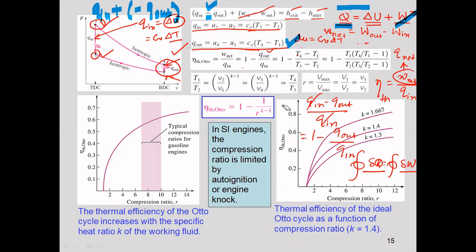Okay. So if you have an engine, in that engine, even if you do not conduct an experiment, you can measure the volume. Right or not? Even if you do not conduct any experiment, simply you can measure volume without conducting any combustion, etc. So if I can convert the temperature ratio in terms of volume ratio, then we can easily guess what is the efficiency. Because you see, if we keep the efficiency in terms of temperatures, then without doing experiment, you cannot estimate what is the efficiency. Do you get me?